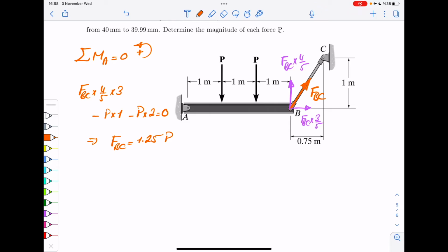So from that, you would connect, let's say, a strain or a stress in the beam to P, okay? Now, for this particular example, by the way, let me just write it on the side. We know the material properties. It says it is made from a particular steel that we know. So let's say Poisson ratio is 0.32, and E is 200 gigapascal. Okay, so if you need, you can use that.